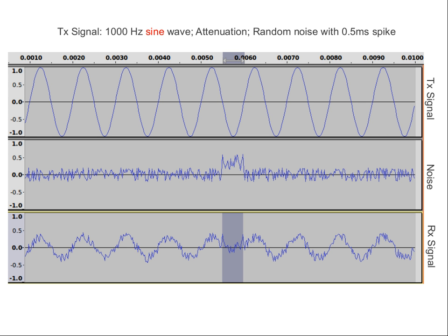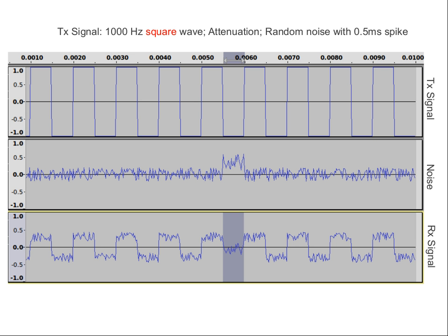Remember, last week we had signals with 2 components and 3 components. What about this other signal? How many components? The square wave. Go back to your lecture notes. You remember if we keep adding components, 1 plus 1/3 plus 1/5 plus 1/7, and so on, if we add an infinite number of components, we get a square wave. So the first one in theory had 1 component, and the current one has an infinite number of components.